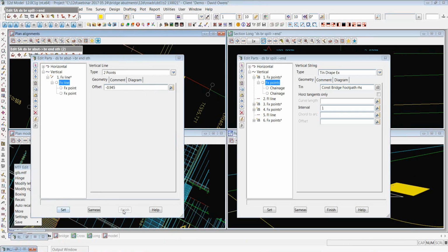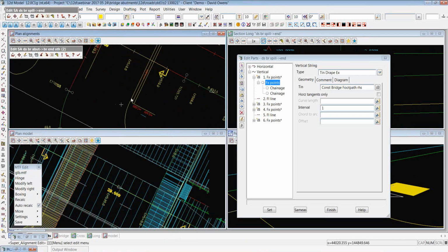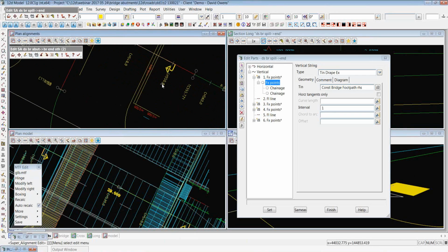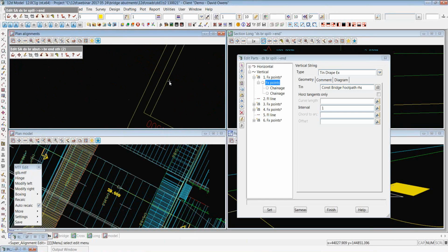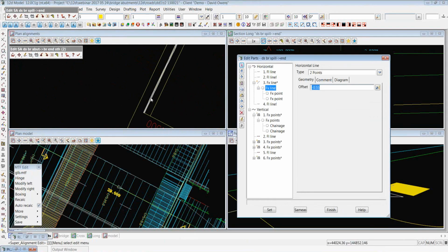And the alignment was set by the bridge guys when they said where they wanted these things. So that's just a straight line, and really there is nothing to it in terms of horizontal. But that headstock alignment is sitting along the centre of it, and the top of the stone pitching is obviously going to run along the face of it. So there's an offset there in horizontal, basically half the width of the headstock over here. So it is all still related together. If anything moves, it's all going to move together when you string it all together into a chain.